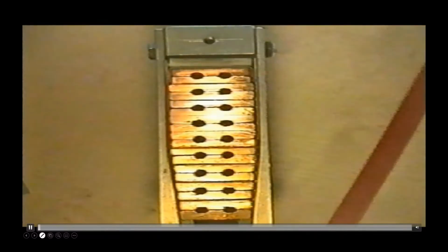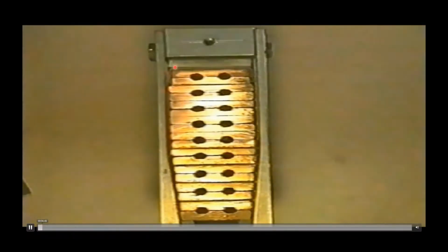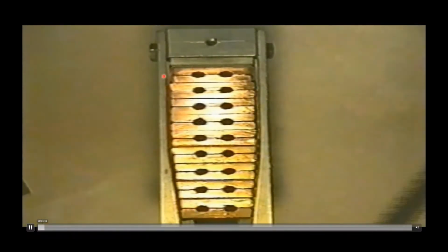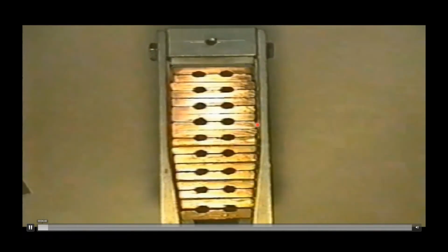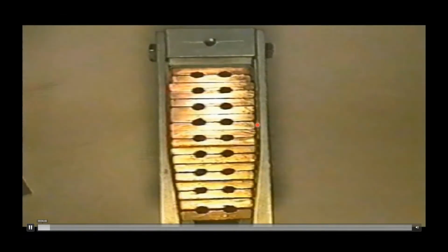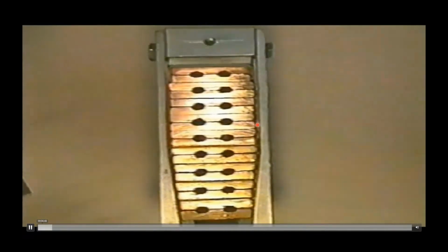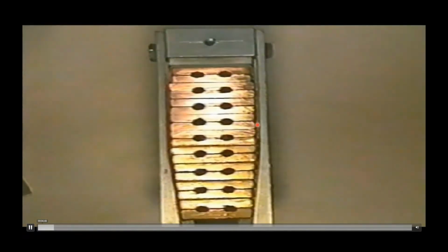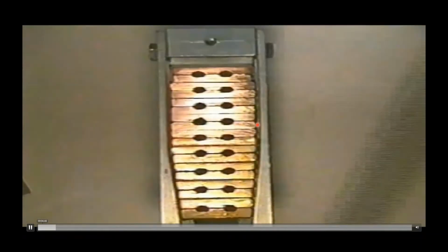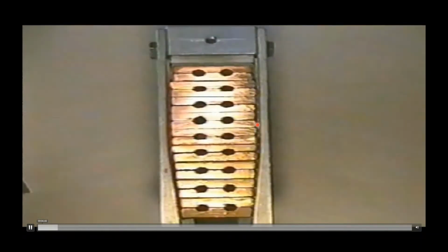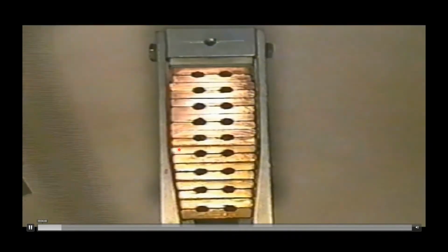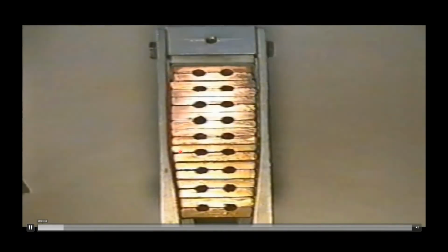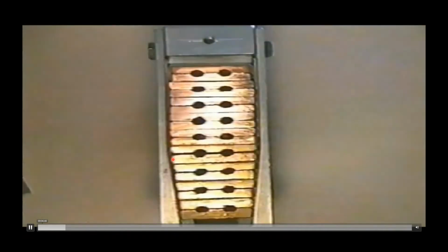So what you see is the coil stack. Well, this is the cross section of one of the slots. It's a 660 megawatt rotor. The speed that the coil stack is turning is 42 RPM, which is very close to what you have in your power station as a bearing gear speed. And you can clearly see the movement of the copper stack. Yeah, can you see it here?